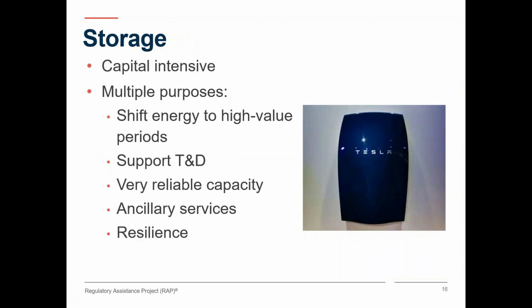Storage is also capital intensive. We use it to take excess energy in low cost periods and save it for use in higher cost periods. We can locate storage where we need it, and that way avoid generation, transmission, and distribution costs. It's also very reliable and very fast responding when we need it, much better than any conventional power plant for providing ancillary services. Traditional cost allocation techniques have trouble dealing with a capital investment that has all these different purposes and benefits.